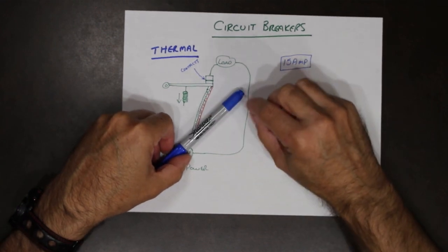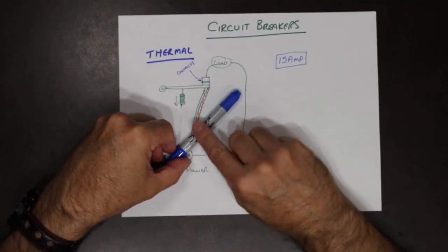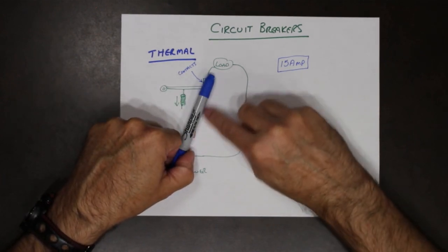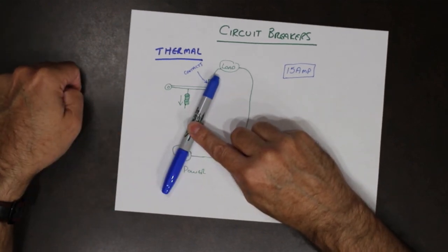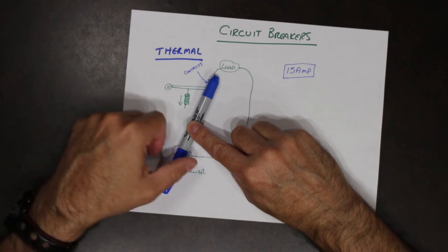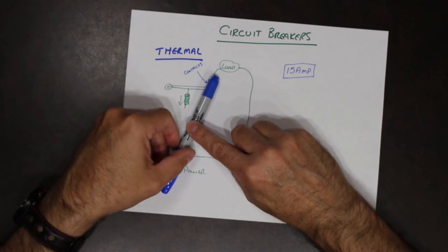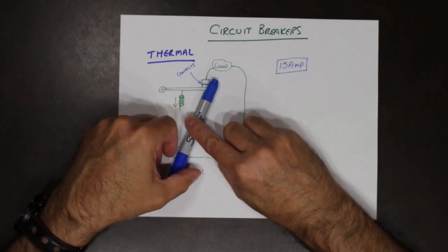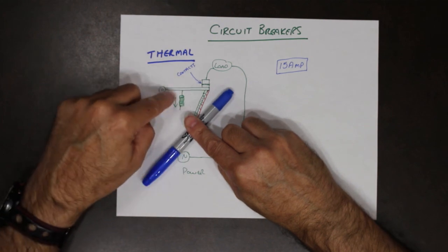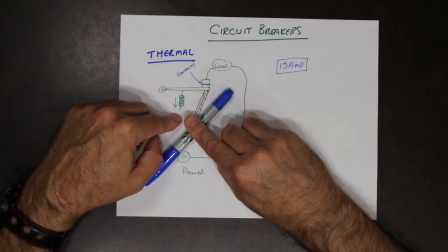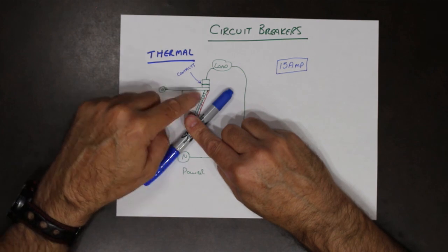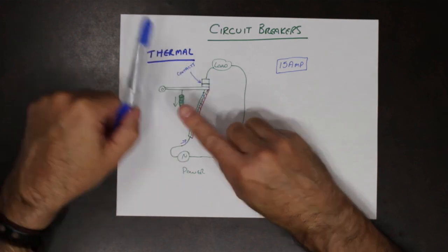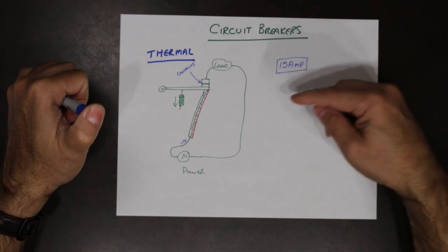Typically now there's a little reset. Once the contacts cool, we can lift up this arm and put the metal piece underneath, and we're all set back up again. And again, as the current increases past the limit, these things will bend and the contacts will be opened by the spring. Then once everything cools off, the arm is lifted back, contacts are closed, and this is put back into place. So over and over again, we can use this breaker.